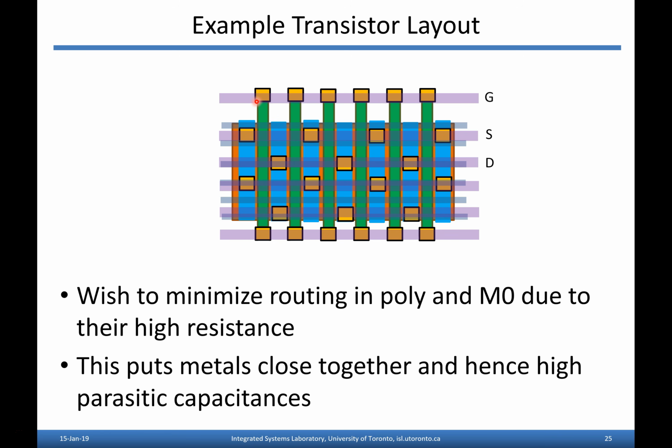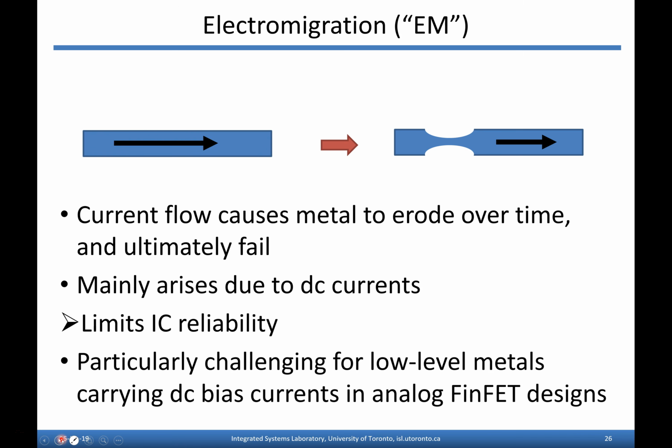So it's just tough, basically, to make all these contacts in such a tiny area and get the current in and out of there without having a bunch of capacitances show up as well, right? So another issue that was always there in planar technologies, but it's just getting particularly bad in FinFET technology. And this is not really anything necessarily about the FinFET geometry. It's just the shrinking technology, right?